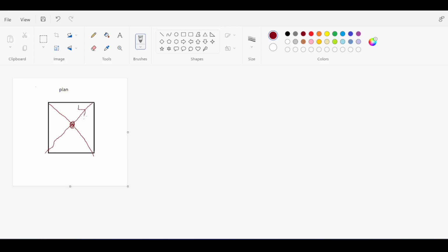Like you have here your couch, you have here your kitchen, maybe you have here nothing, just an empty room. So usually the weights are not distributed perfectly symmetric, which means that the center of mass, which is basically also the center of the applied force, is going to be shifted on one of those axes or even two. And some codes require you to apply something called the accidental eccentricity when you calculate a force, which means that not only will the earthquake move the structure back and forth, but it will also twist it counterclockwise and clockwise.